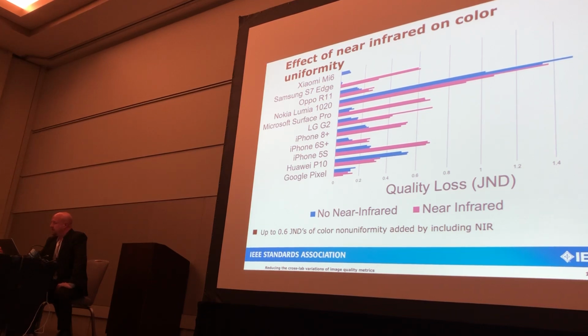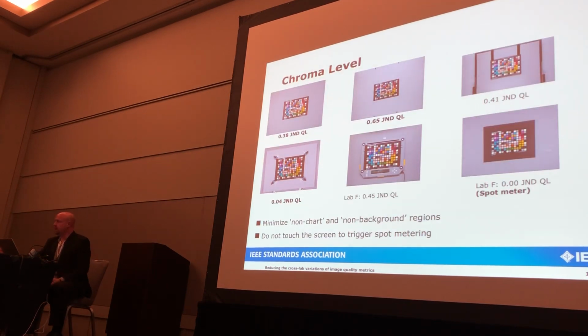Superior filtering and processing can totally eliminate color uniformity issues. That device proved it. We have plenty of environments that use daylight lights without infrared. So calibrating and testing in both of these conditions is part of a complete characterization of an imaging system. Chroma level is a metric which can also be impacted by infrared contents. Humans like a little boost in chroma beyond accurate chroma of reality.